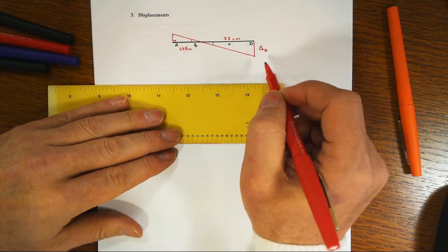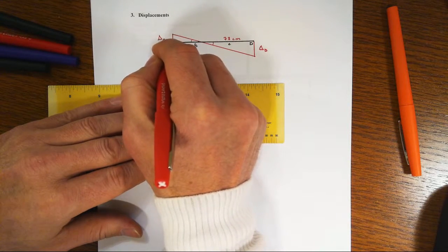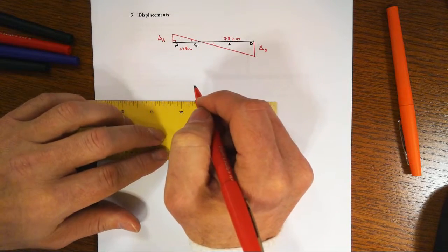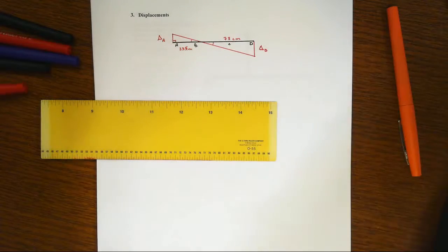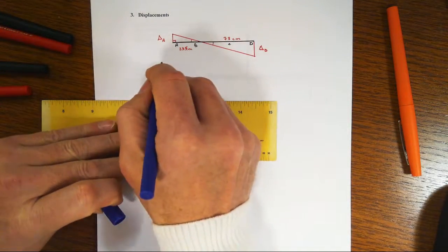So notice that what we're trying to calculate is the delta D out here at the tip corresponding to the yielding that's happening at point A. And so the displacement that happens at A in this case is being caused entirely by the elongation of that rod. Now it won't always be like this, but it is certainly the case in this instance that will turn out to be where we're at.